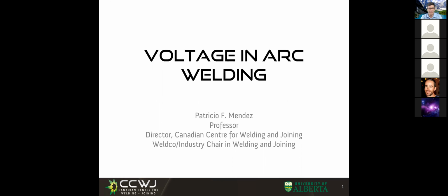If you look at all the exams, you're going to see some questions about the heat affected zone, about some basic questions about metallurgy. That is what we start to discuss. You'll see questions also about voltage for sure, how to calculate a voltage in TIG or MIG, which we are seeing now. And also questions about metal transfer that you'll see. We discuss a little formula that helps us estimate if a process will be on spray transfer or globular transfer.